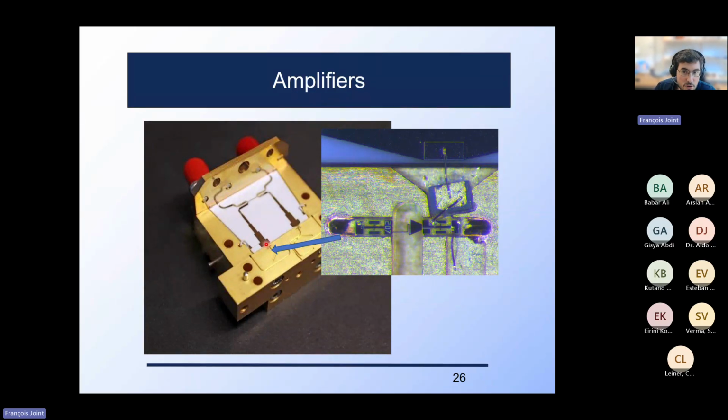And it carries also a bit more functionality. For example, the PCB contains some impedance transformers. The impedance of the SIS is generally not the same impedance that you can carry on an SMA cable or K connectors. You need to have 50 ohms. So here we have a bit more impedance transformation. It also helps to bring the DC line. So we have a superconducting bias T attached to this PCB that allows us to bias the SIS without compromising the IF signal transmission.